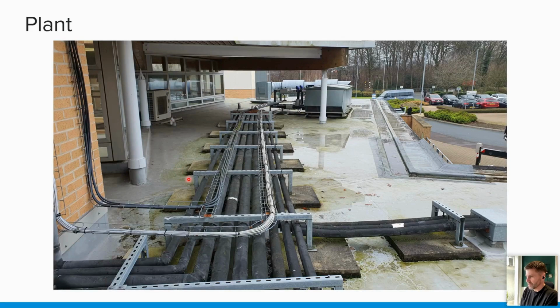So is it possible to jack it up a bit, get some waterproofing underneath, or do we have to look at a bespoke detail of boxing in these pipes? But obviously then we've got to consider that the pipes are going to need maintenance and things like that, so we need to give access to them. So yeah, it's a bit of a headache when you come into putting a solution together.